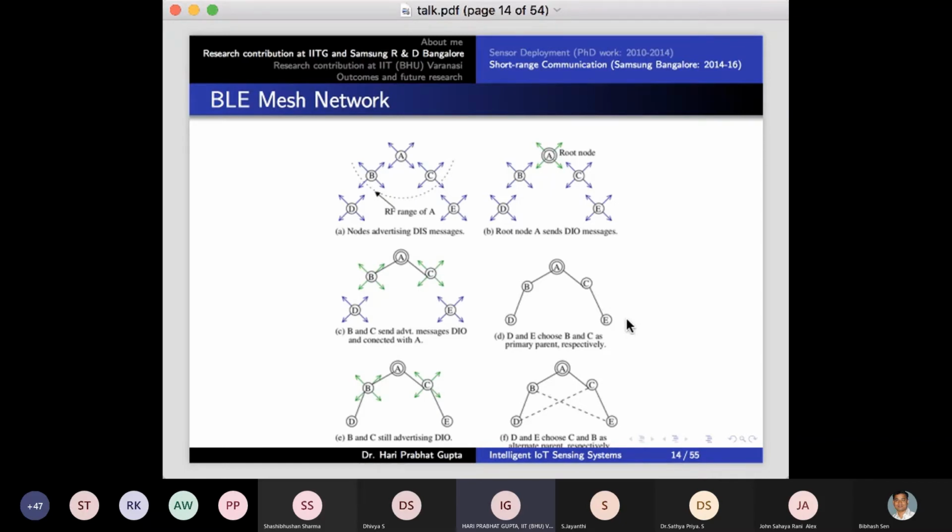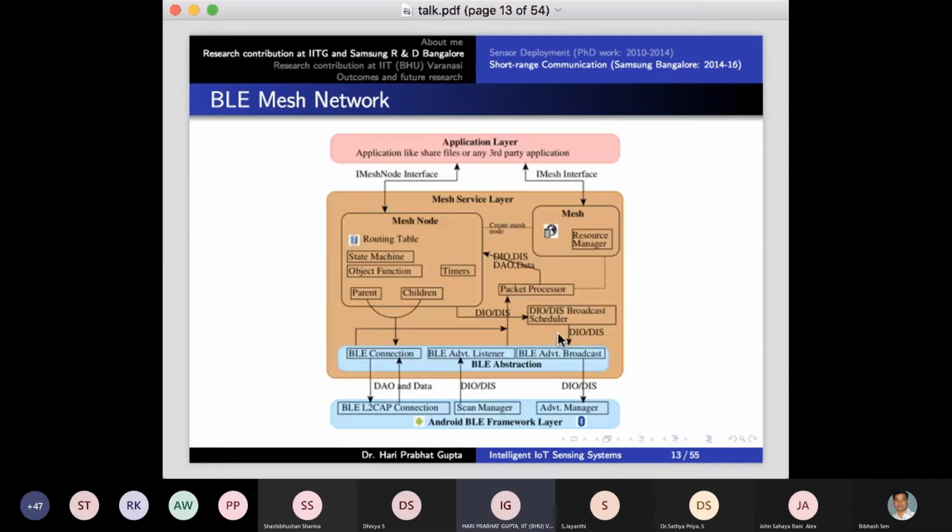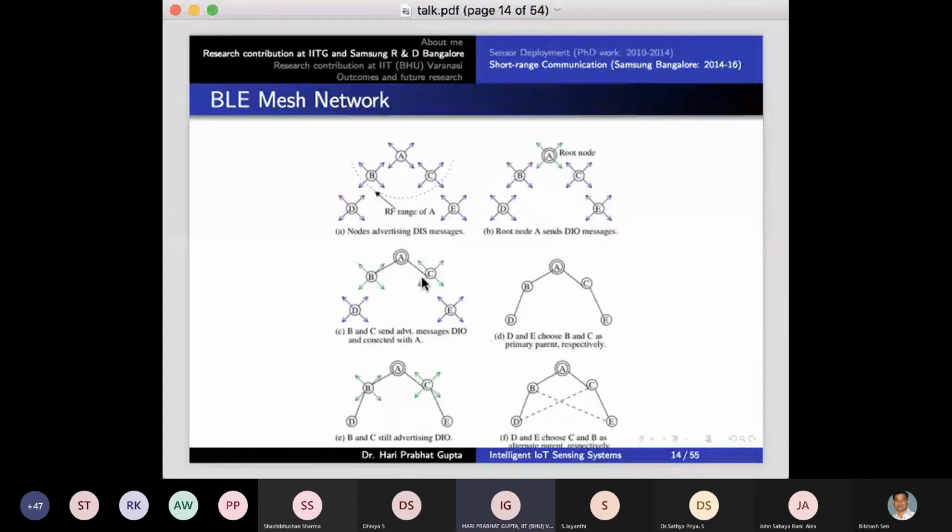Because they create a sandwich layer between the core Bluetooth protocol stack on Android and your application, and that layer provides the one-to-many connectivity, while default Bluetooth supports one-to-one. So here we also designed in the previous framework a broadcaster for multiple connections and the objective function, where one-to-many properties are there. So this BLE mesh network is also suitable where the Zigbee communication protocol is used.